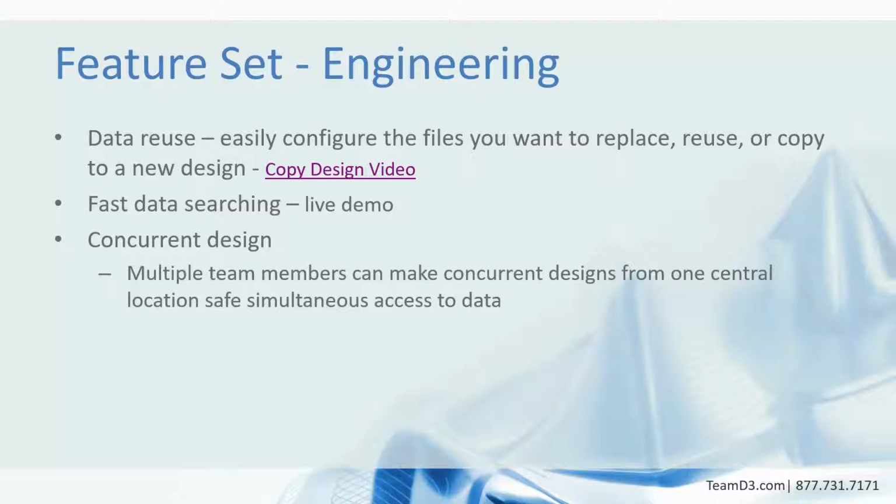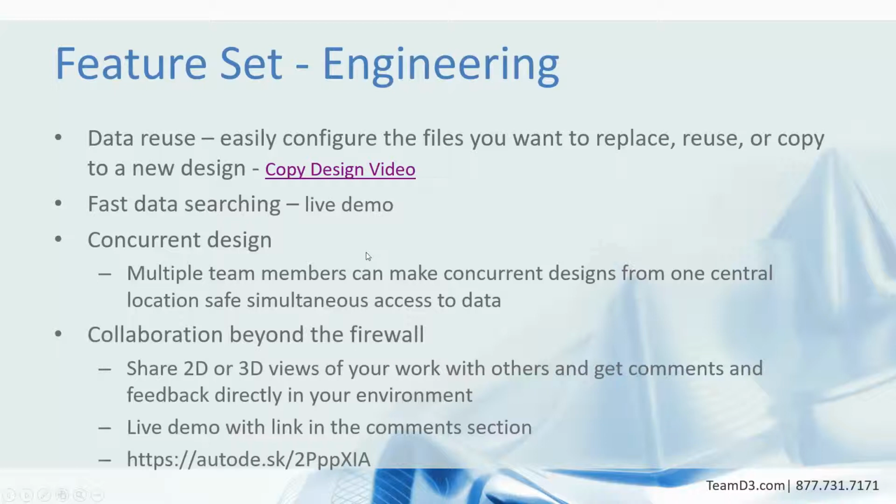And then when one of them checks it in, the other one gets notified inside their browser in Inventor that it's been updated, and they can right-click and update it from the Vault, and they get their current ones updated, and we're not stepping on each other's toes to make that happen. So concurrent design, that's a big one for large assemblies.